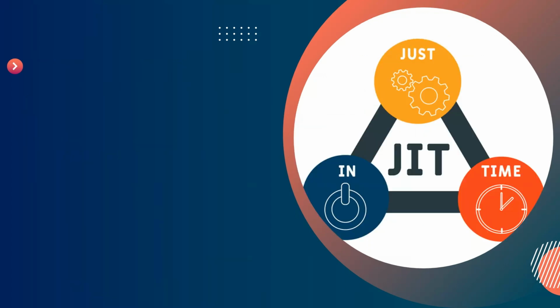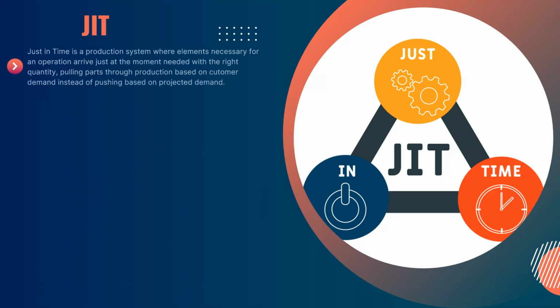Let's go to the next slide and understand the next tool, that is JIT or just in time. Just in time is a production system where elements necessary for an operation arrive just at the moment needed with the right quantity, pulling parts through production based on customer demand instead of pushing based on projected demand.